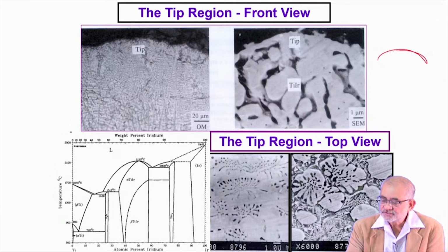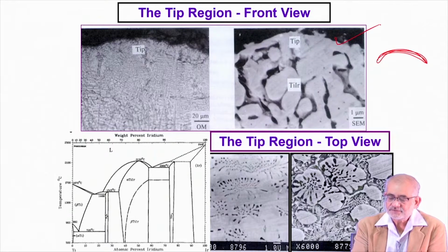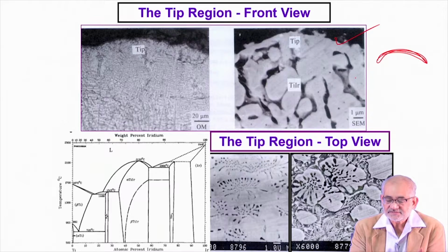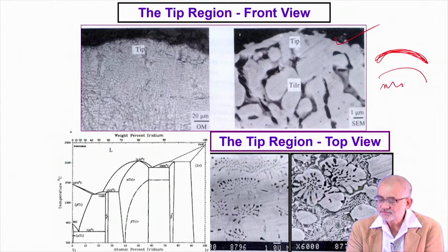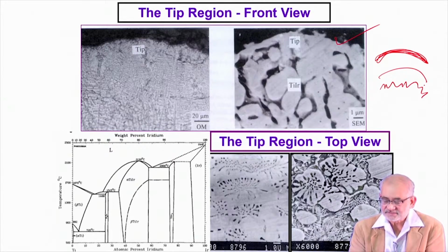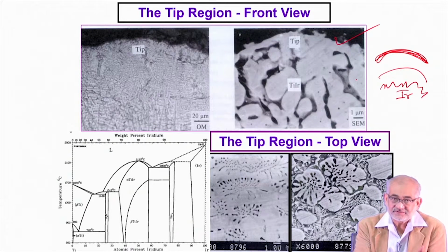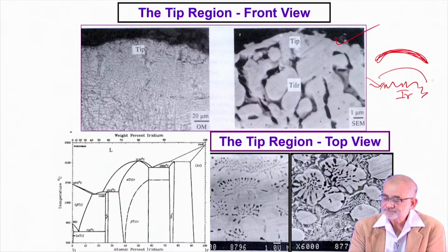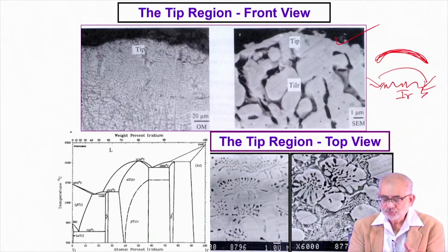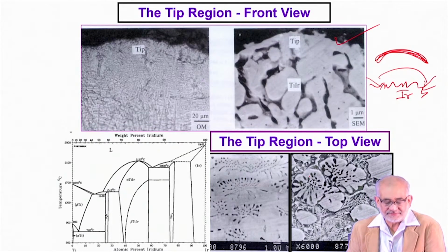So compared to a smooth surface like this, if you create a surface like this, you can immediately make out that these deep fissures and intentionally added roughnesses make the specific surface area of this tip much larger than a component which has a smooth surface like this. So instead of having a smooth surface, we want the surface to be as rough as possible, so that the specific surface area increases. And this we are trying to do on iridium, which is not possible directly. So we use laser surface alloying as a strategy to create that titanium-iridium rich layer, and then use a specific etching process to create such a two-phase aggregate which is amenable to etching.